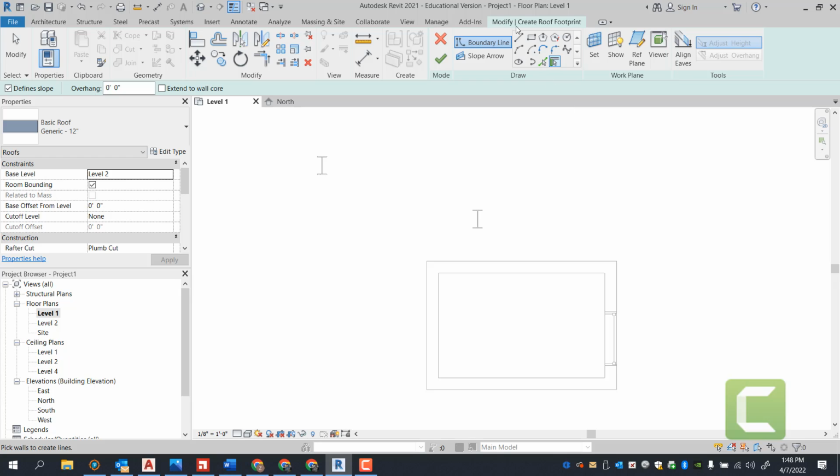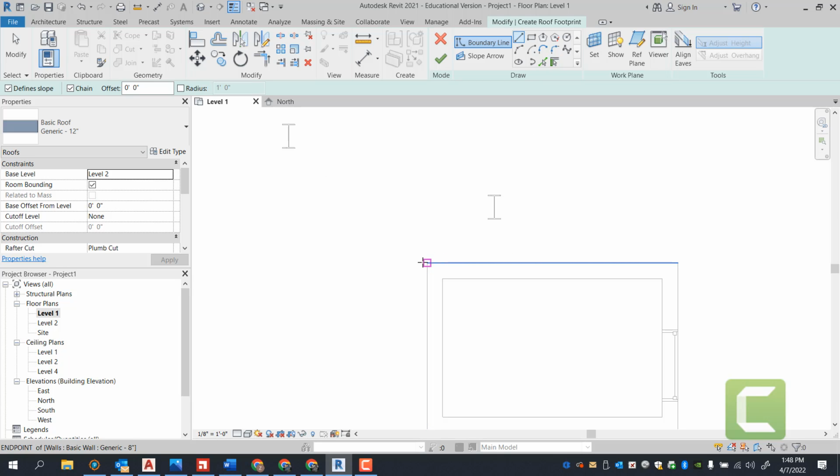I don't want you to spend time going, hey, I'm going to use the offset command, I'm going to use line. If you're doing this, where I'm going to have to go 2 feet over, then draw a line, you should be using offset. Do not spend time drawing so much. Does that make sense? If you want to get a rectangle, you're going to do pick lines.